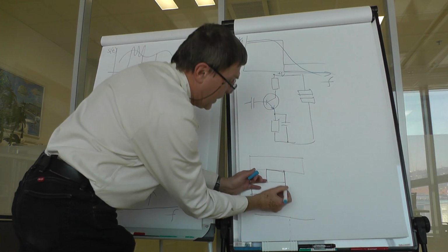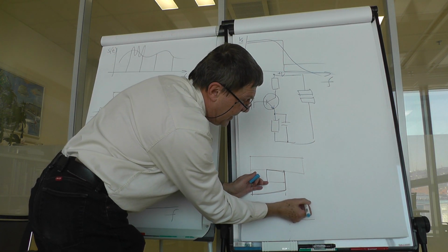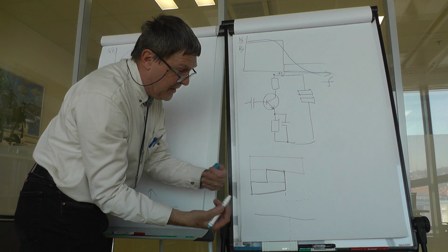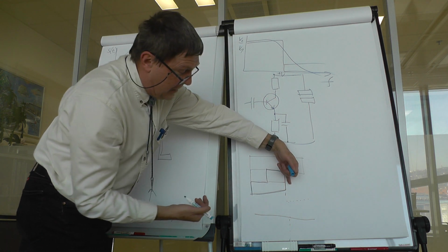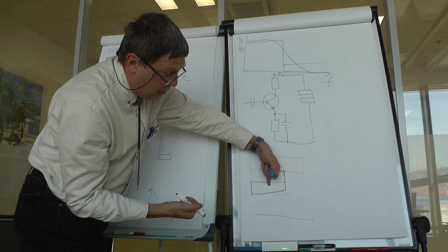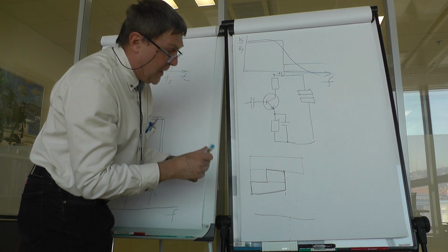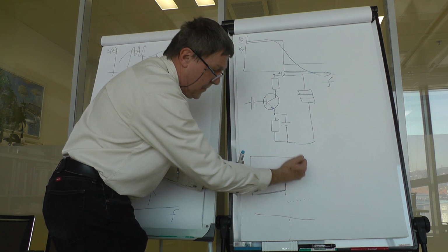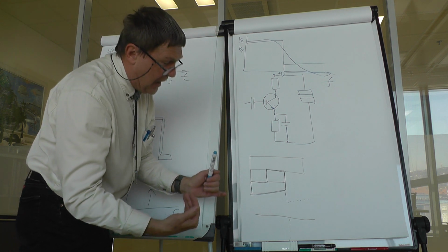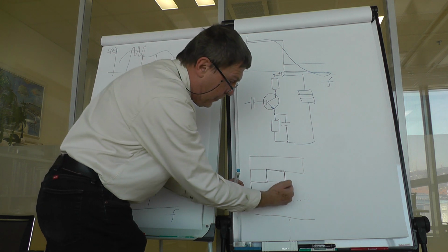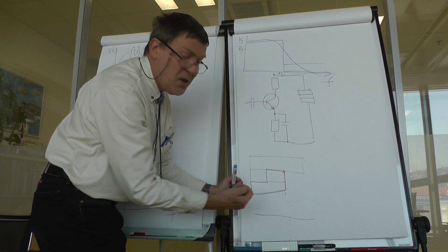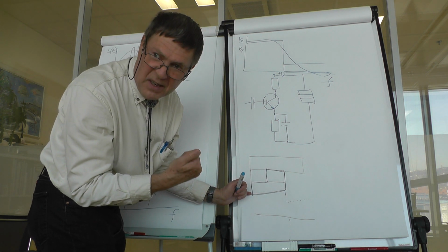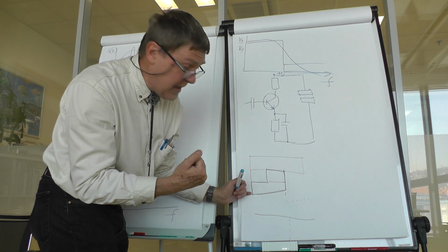So those frequencies that are out of the band, still present in the signal, are mirrored at the edge back to the band. So if you, for example, have a signal from 0 to 300 Hz, and you apply a sampling which is enough for 200 Hz, so you would have a 400 Hz sampling frequency,